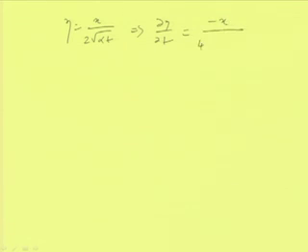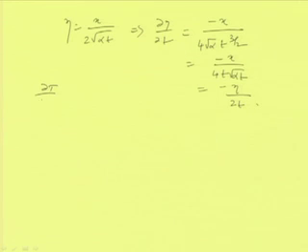Now, we have η = x/(2√(αt)). From there we can write ∂η/∂t = −x/(4√α t^(3/2)). This can be written as −x/(4t√(αt)), and we replace this by −η/(2t). So, we can then write ∂T/∂t = −η(To − Ti)/(2t) × ∂y/∂η.